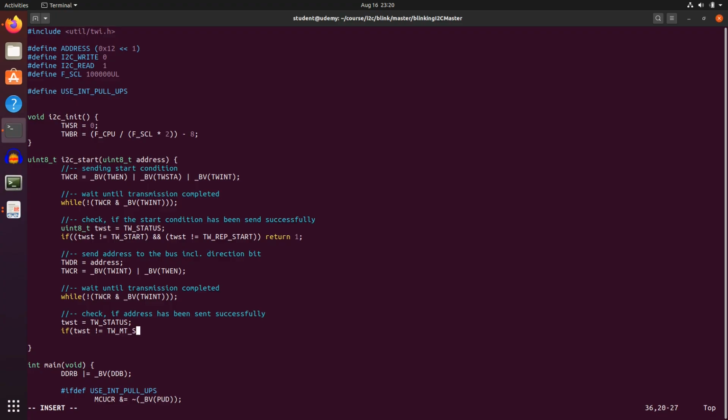TW master transmitter, slave acknowledgement. Either this one, or TW master receiver, slave should also be acknowledged. If this didn't happen, I have an error and a return 2. Otherwise, no error occurred and I can return a 0.